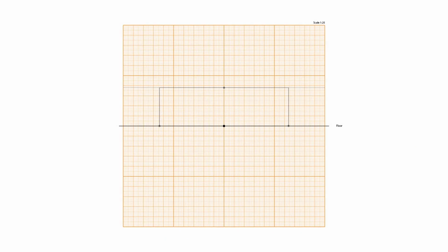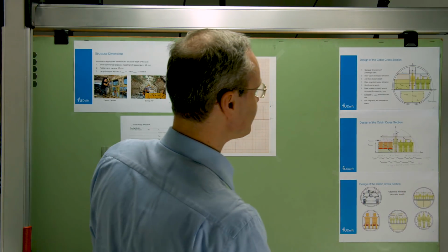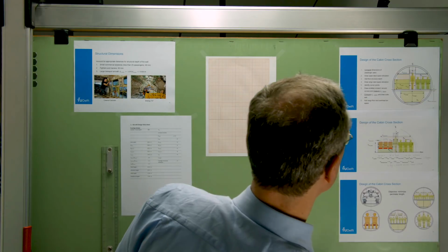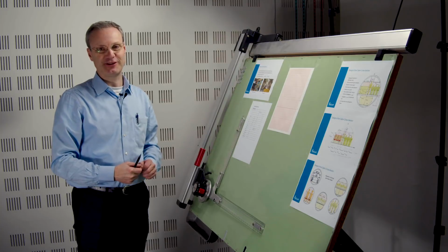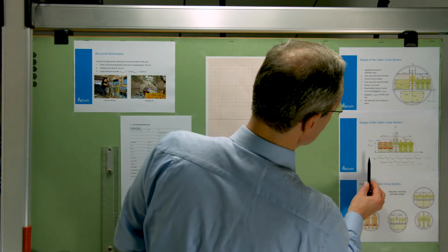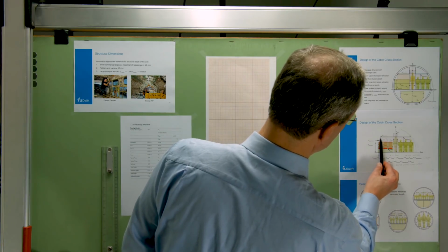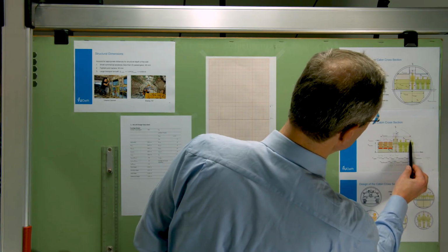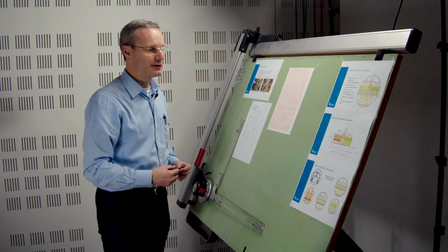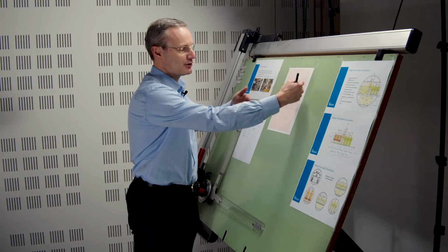And then we have the block for the shoulder height. Now we have just drawn this block, width of the cabin, shoulder height, all inclusive. Now we need to take the headroom, and the width of the headroom is centered around the seats. One edge lines up with the middle of the most left-hand seat, and the other one lines up with the center of the most right-hand seat. So what we need to do, from the edge of this block, we need to go inward on both sides.